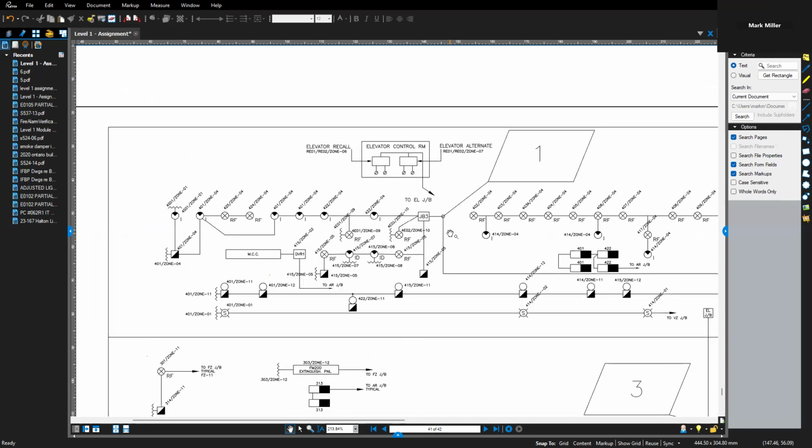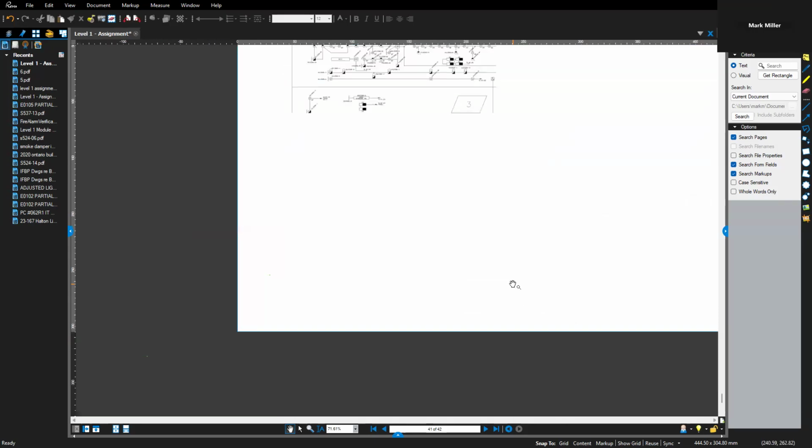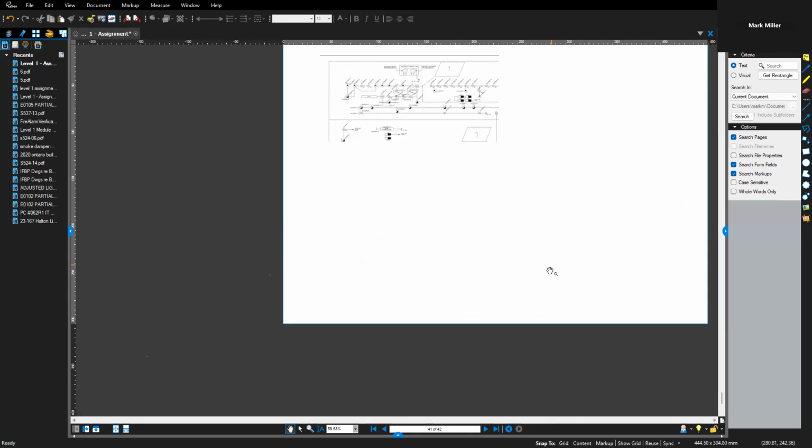I want to know what zones are at that point and the number of conductors in that conduit. So we're going to take our imaginary Mr. Bandsaw and we're going to slice through that conduit, and what is going to be in there? Right. So I can see that my fire alarm control panel is way down on the ground floor, maybe in the basement.